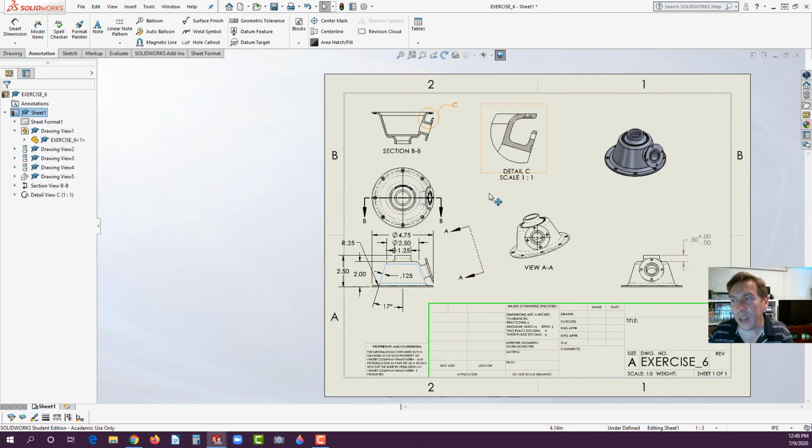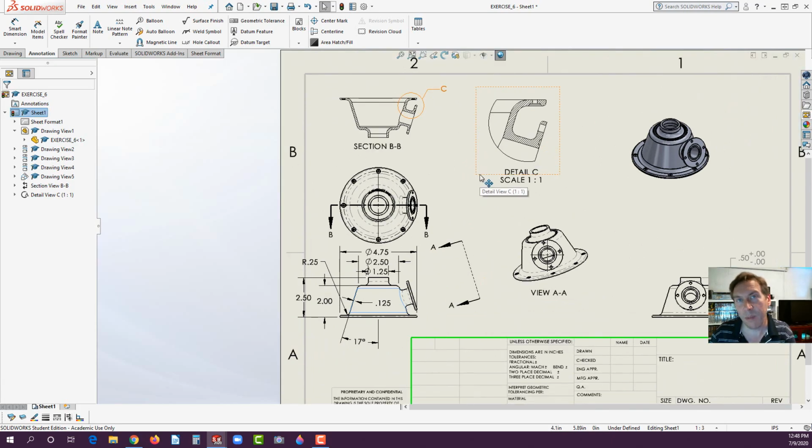Zoom out. Now you can actually move that much of the time to a different view as long as that view is parallel. If the view isn't parallel to how it was drawn out, like for example, if everything was drawn on the front plane, and then all of a sudden on the right view you wanted to bring up these same dimensions, there's a high likelihood that you're not going to be able to see them because they're relative to the view. You're only seeing what's parallel to the view here. Okay, now here's how to move a dimension.